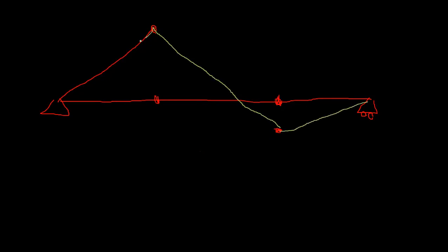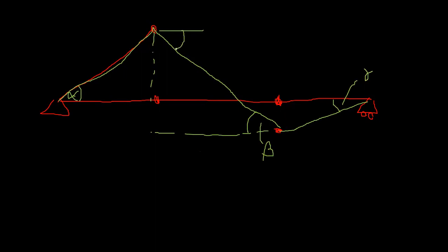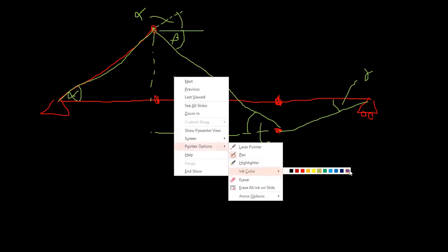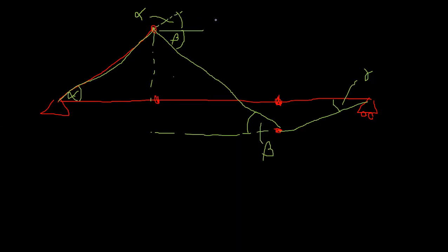What we know is this, right? You can take this as alpha, this as beta, and this as gamma. So this would be alpha. You extend this part, right? This slope is not equal to this. So I need to find what alpha, beta, and gamma are so that I can find the relative displacement. Here the relative displacement, compared to this part, has moved clockwise, that's alpha plus beta, right? This is gamma, this is beta, and this is gamma.